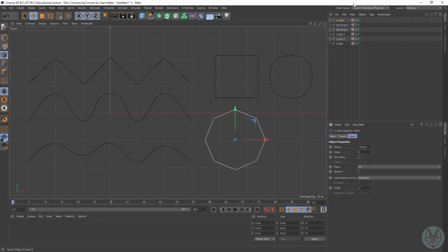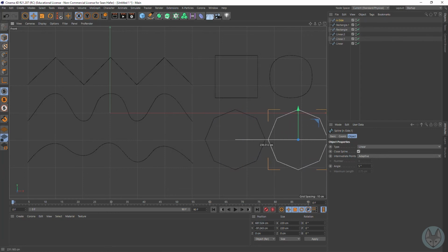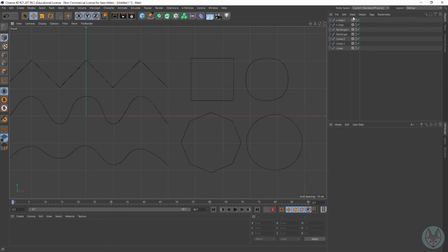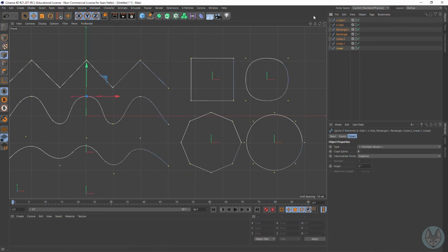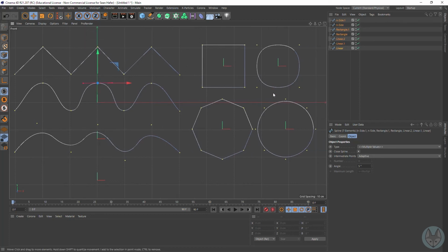And if I took that, made that editable, so we can see our points, and then created a copy of that by Ctrl or Command dragging over. Now we can see what happens if we take that and turn that into a B-spline. Grab all of these guys so we can see all our points. So now you can see with those points serving as an even influence around, it becomes a perfect circle, right? And that can be as low as 6 points. 4 is just not quite enough, just on the way it works.